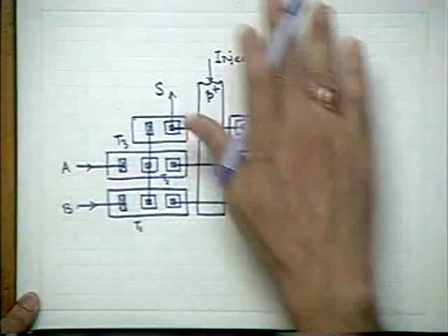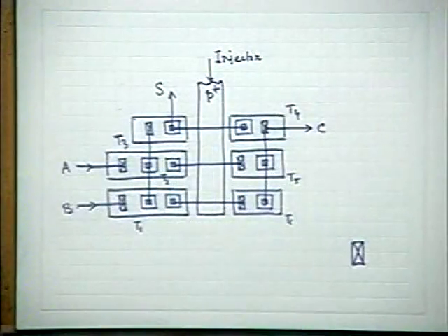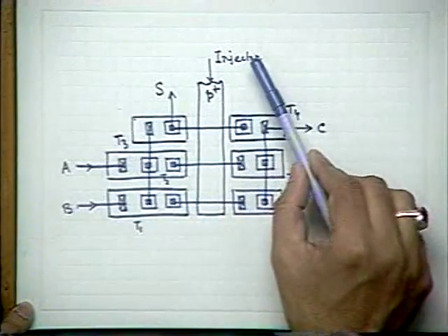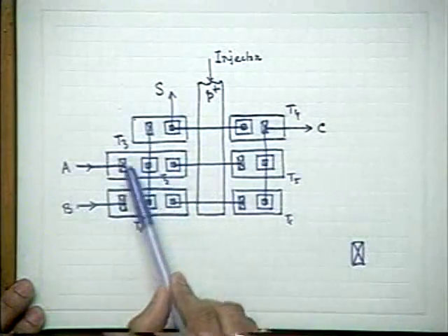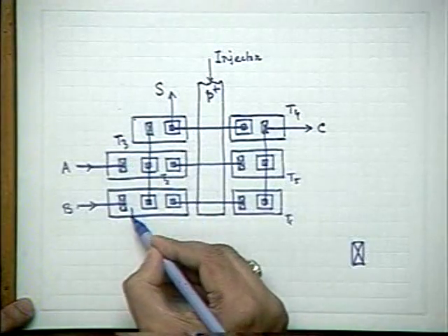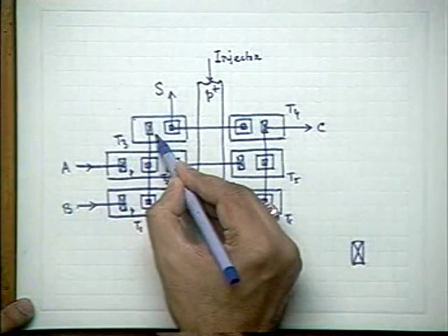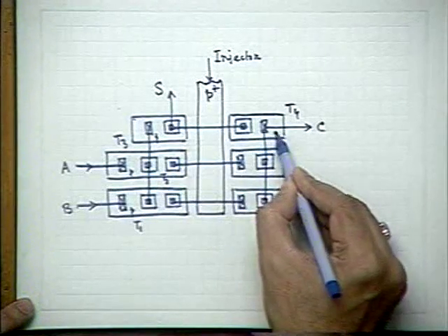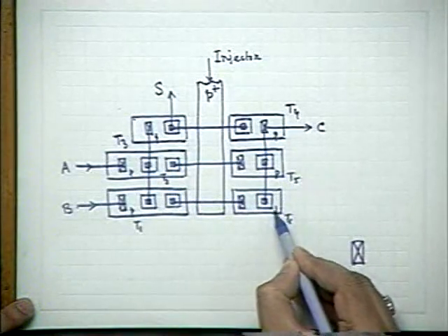If you remember the diagram, this main film, the semiconductor wafer substrate, is N+, on which there is an N-type epitaxial film, and then we have a P+ diffused region, which is quite wide, maybe quite strong, because it has to supply a lot of current to the different transistors. Okay? And on either side of it, you have placed the different bases. Each base is usually lightly doped P regions. Please remember, these are all P-type regions.